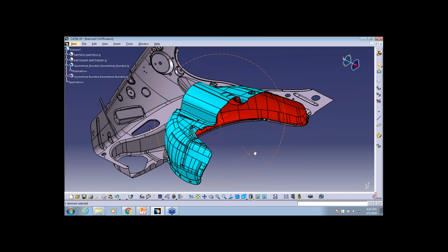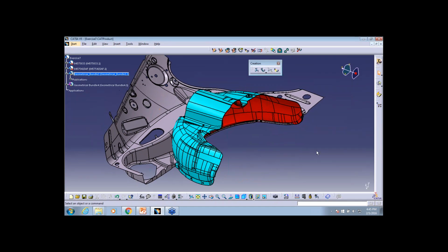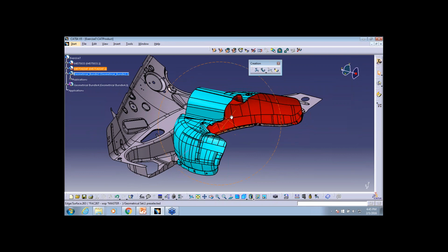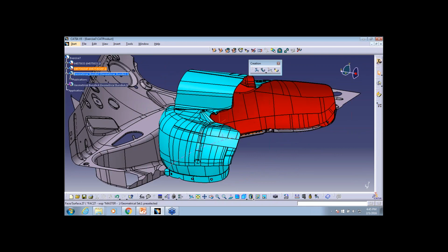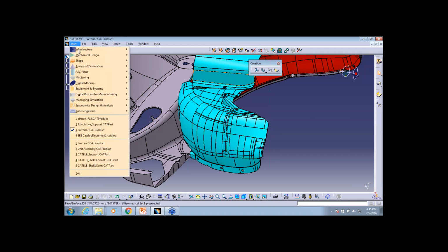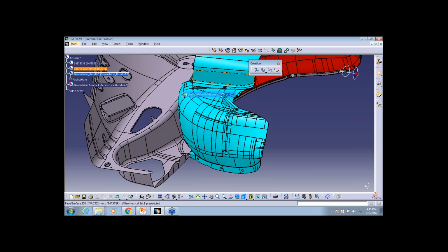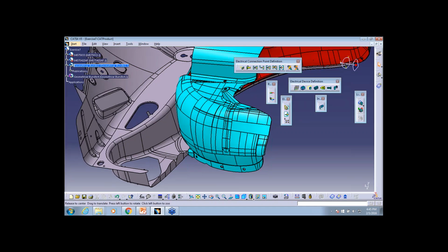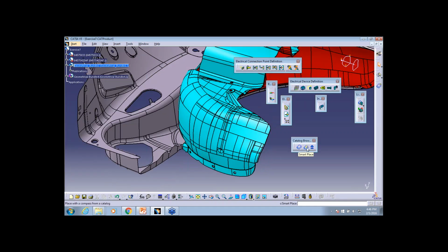Okay. I'll just activate this. I'll show you how to bring your standard components into this. So I'll jump on. I want to bring in supports. When I want to bring in supports like clamps, a clamp is a device, it is not a harness. So I will get into the electrical assembly model, where we have one command called smart placement.